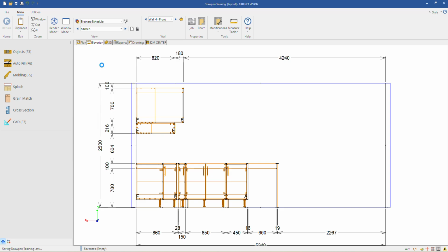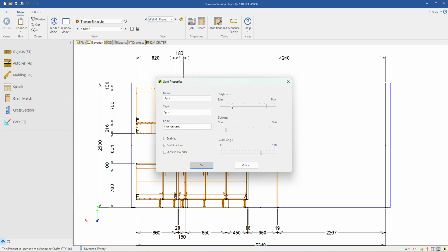To do that, right click anywhere in the open screen, and you'll see there's that little add light option. If you press that, it's going to bring up this screen. Now I can go to properties. I can give the light a name. I can change the type. For this, a tube light usually works best because I can modify the width, the height, and the length of it. So that's continuous. Correct. So I can select the tube.